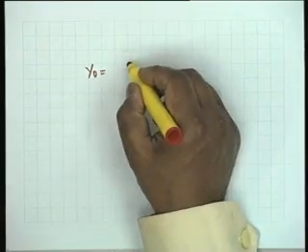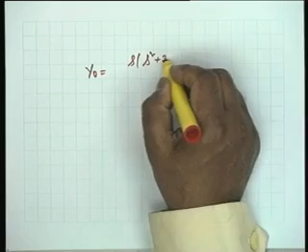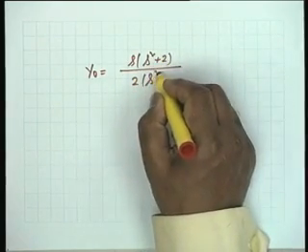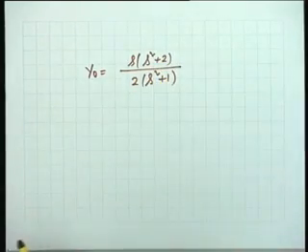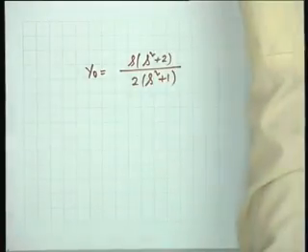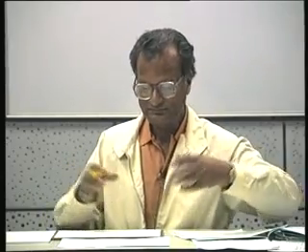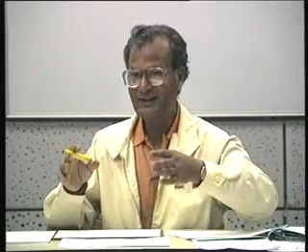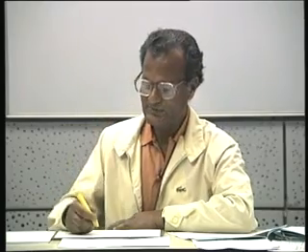Okay. Anyway, so we know G equal to 1, and incidentally we also know what is y0. y0 is s times s square plus 2 divided by 2 s square plus 1. And at this point many of you forget that a specific form has been wanted. You can expand this in partial fraction and get a realization, but that will not be the correct answer, because it specifies that we synthesize Z0 in a Foster series form. So, do not realize this.